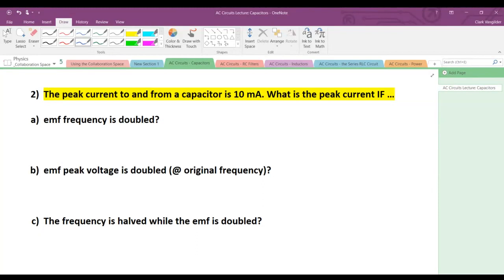And so you have, I guess, in general, what we just did, your current through a particular thing like a capacitor would be that formula. That's just Ohm's law business here. And so you're going to have VC over XC, which just means you're really just going to get a 1 over omega C, which means you're going to have omega C VC. That'd be just jamming those equations together as they go.